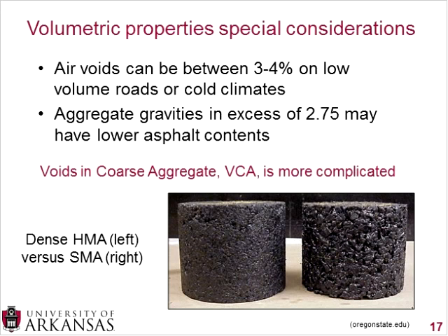So first, starting out with the air voids, you can actually have a range between 3 and 4% on low volume roads or cold climates. As the volume goes down, as the climate gets cooler, you can actually start dropping those air voids.